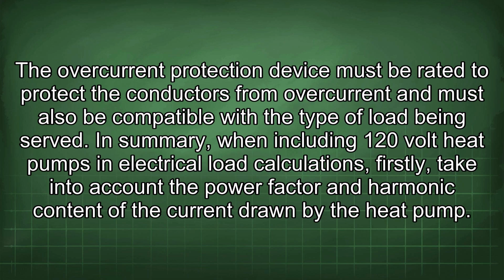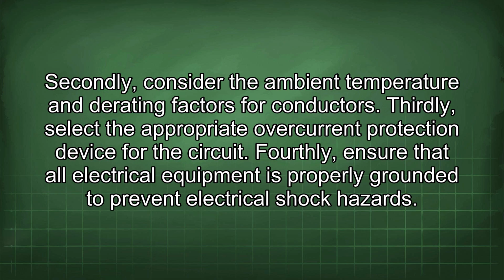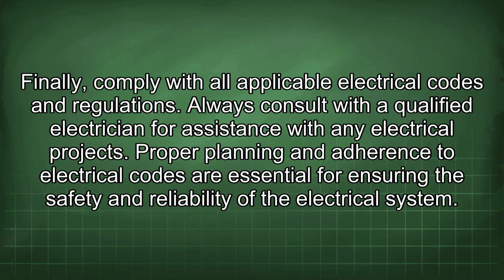In summary, when including 120-volt heat pumps in electrical load calculations, firstly, take into account the power factor and harmonic content of the current drawn by the heat pump. Secondly, consider the ambient temperature and derating factors for conductors. Thirdly, select the appropriate overcurrent protection device for the circuit. Fourthly, ensure that all electrical equipment is properly grounded to prevent electrical shock hazards. Finally, comply with all applicable electrical codes and regulations.